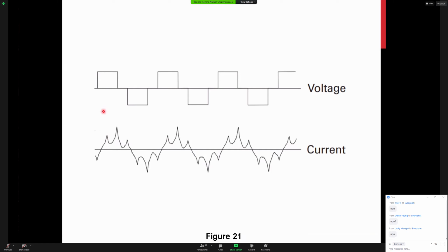If you think about it, instantly we have a voltage, which means we're going to have a sharp rise in current, but then it's steady, so the current kind of dips and starts up again, and then it goes down to 0, and we get a little transient switch here. So this is actually what the current waveform looks like on the secondary side, so going to the motor.